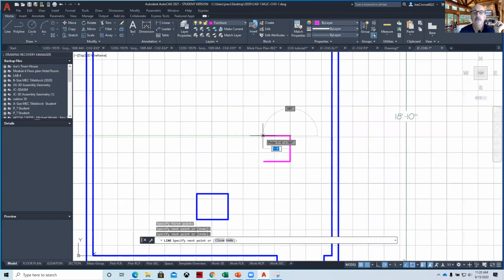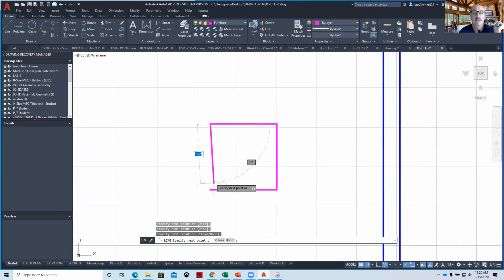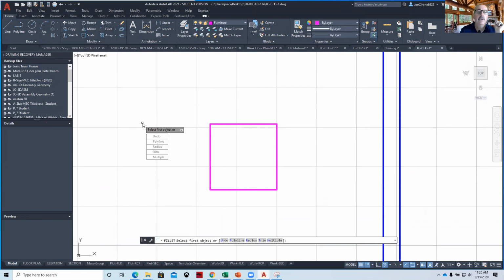It's easier if you just zoom in. So sometimes when people are like this, I'm like, no, no, no. Get closer so you don't need to get glasses. So that's our 1 foot 8 inch by 1 foot 8 inch. And then it's got to have an arc that kind of goes all the way across. So if it's 1 foot 8 inches, we're talking about 10 inches for each radius. So we can do a fillet with a 10-inch radius on each side. Fillet, down arrow, radius, 10.